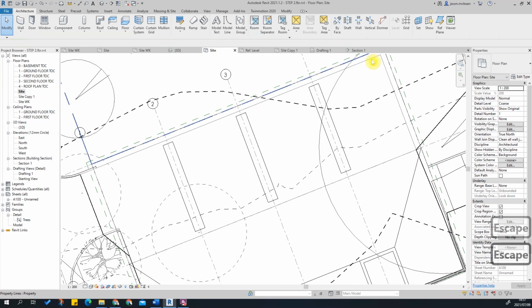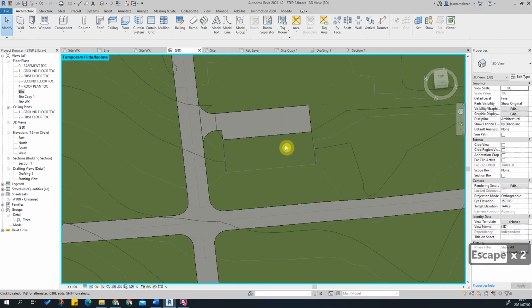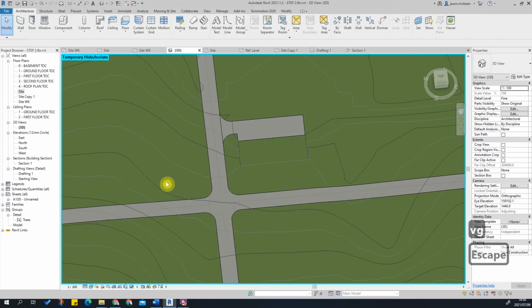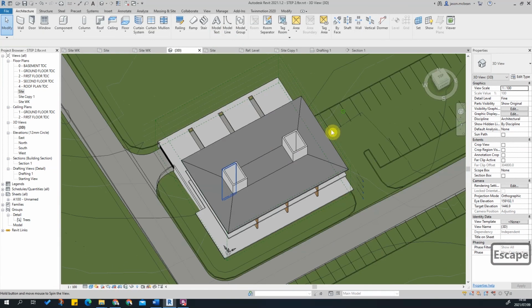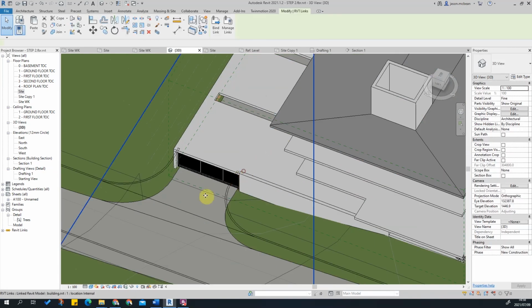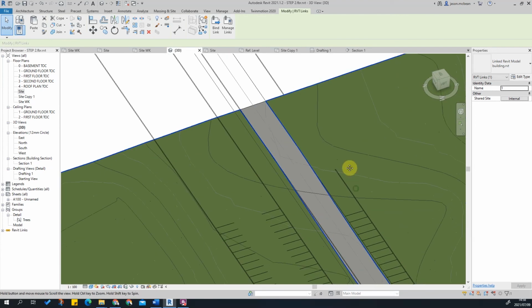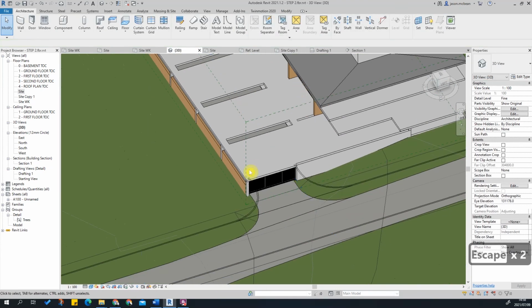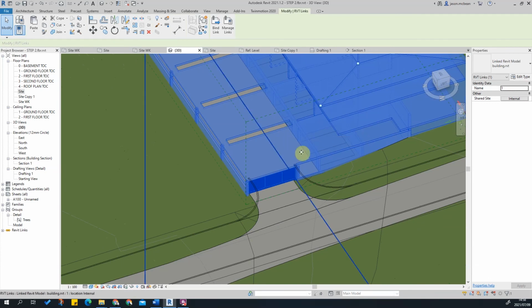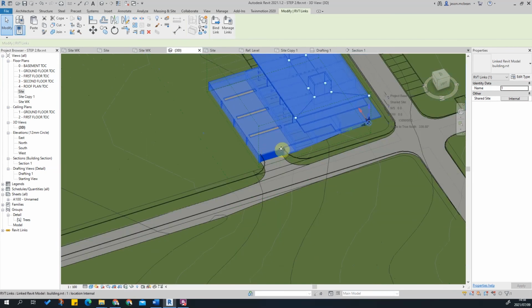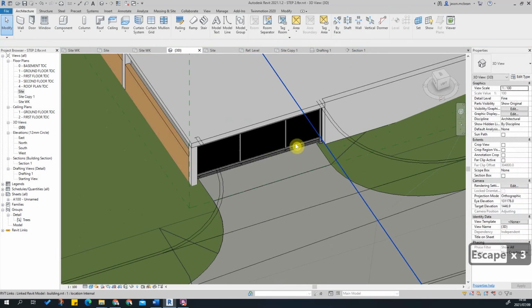So if I go to architecture, this is a covered parking area. If I just switch this back on, reset temporary height, reset this back on. In this instance, we need to switch this off because generally we don't show this roof level above. I'll show the outline of this level above, and I need to just indicate where this gate will go.